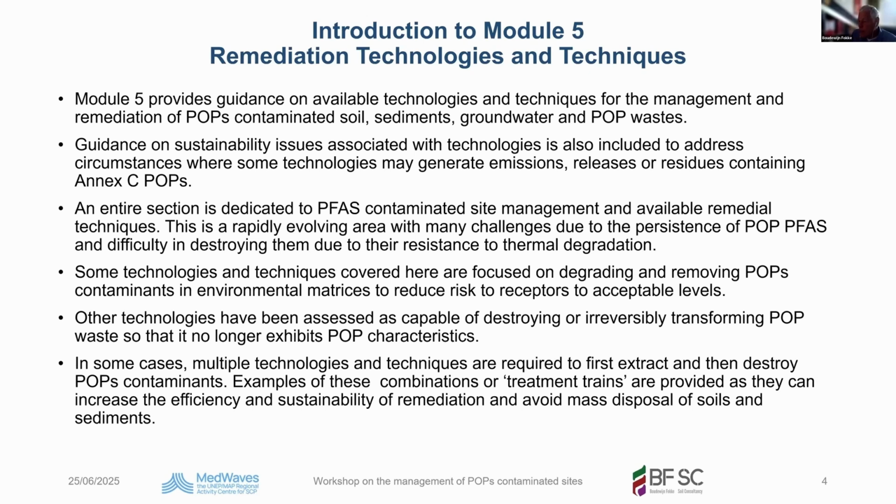So meaning that if you have a contaminated soil with POPs pesticides and it contains rubble or stones or gravel, then the pre-treatment is to take out the stones and gravel. When they are clean, or even when they are contaminated, you can take out the stones and gravel and treat them differently on site, and then only transport to a treatment facility the contaminated soil, all to reduce the contaminant mass to be treated.